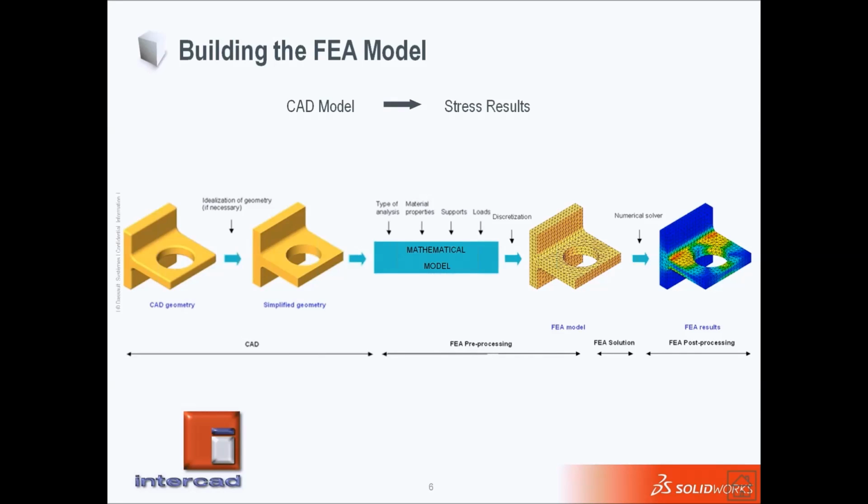In more detail, you decide to design on a CAD geometry, but when you're trying to put it in an FEA solver or FEA modeling base, you can do some simplification. For example, as you can see in this figure, these fillets on the sides have been eliminated, as they do not play an important role in FEA, but having a curved shape will add some complexity to the meshing system.